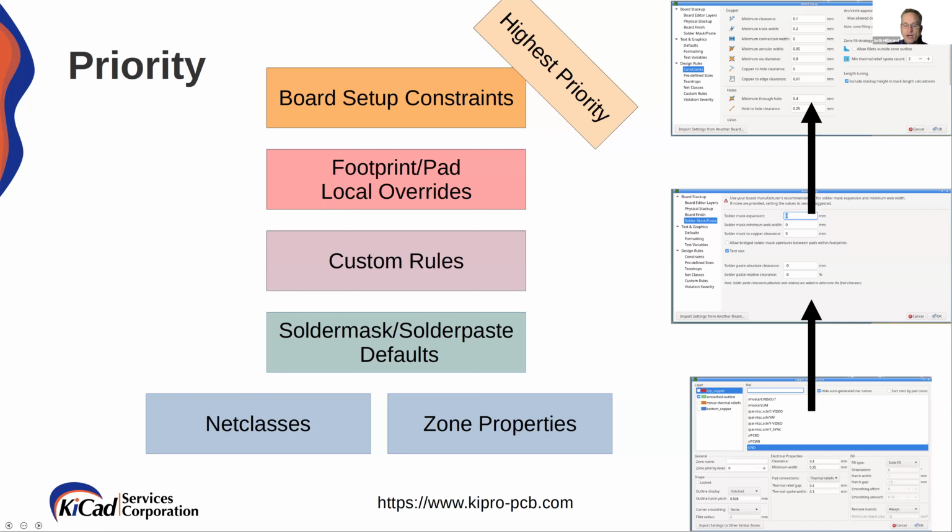So down in the bottom right here, right behind my head, you can see this copper zone properties. This is where you set the zone properties of the copper zone. These are the baseline defaults, and they are the ones that will get overridden by everything else. So if you don't have any overrides, this is what it's going to go with, but anything can change this.